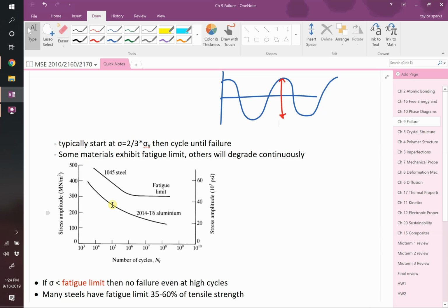So it seems like the amplitude only cares about the difference between the stresses. Yep. So even if you have a lot of stress but the difference is small, it can fail. That's confusing, right? That's unexpected. Because when you bend something, it's the maximum stress that causes the right-hand side of the Griffith fracture equation to fracture. But here what's happening is something different. This is fatigue, and we're going to talk about what's going on in a few minutes. Okay? So we'll come back to it.